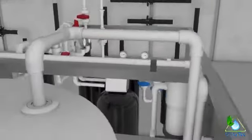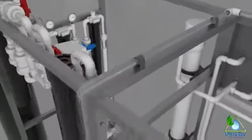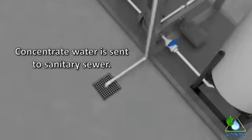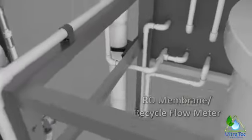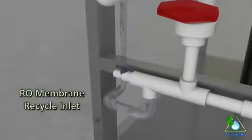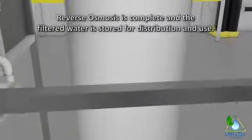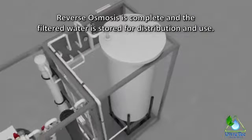At higher salt levels, the concentrate is sent to sanitary sewer, or in some cases non-critical locations for reuse, also known as gray water recycle. In higher water recovery applications, a small percentage of the concentrate water is sent back to the inlet of the RO membrane for recycle. The salt removal reverse osmosis step is complete and the filtered water is stored for distribution and use.